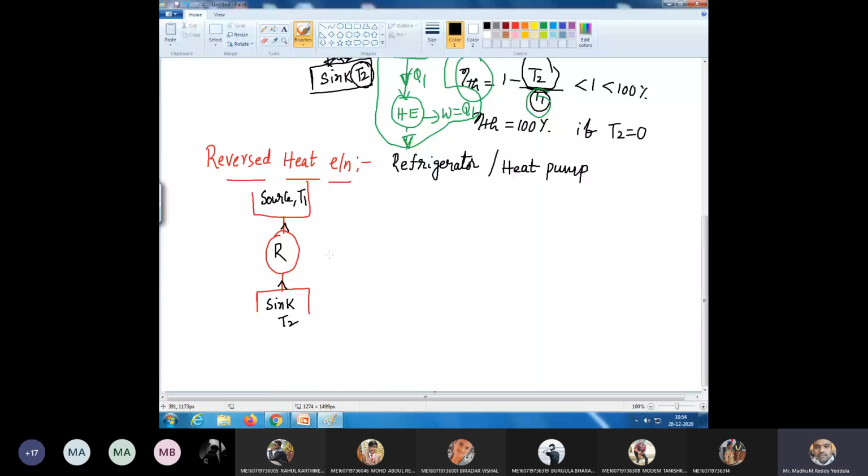So what is the main working of a refrigerator? What will a refrigerator do generally? Let us assume this is our refrigerator in our home. Inside this refrigerator we have the freezer. Here we have a knob, or we can say thermostat, to control the temperature. There is one coil, one pipe, submerged inside the freezer. That is the thermostat end, which senses the temperature inside the refrigerator. Based on that, it gives signals to the compressor whether it has to start or stop, depending on the temperature adjusted by the thermostat.